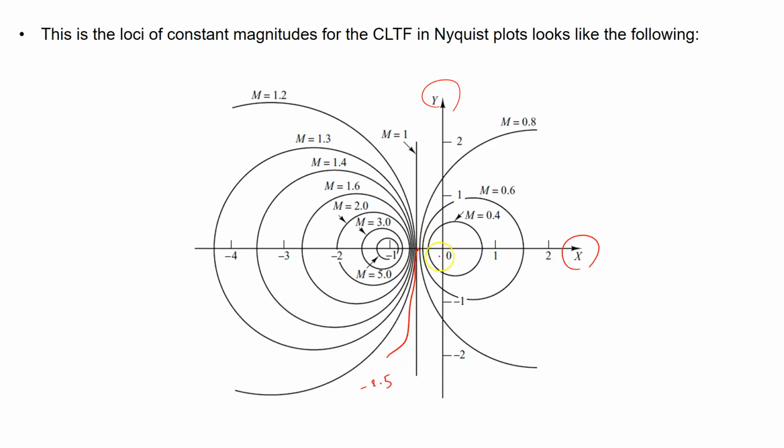So now if I have this on top of that Nyquist plot that you saw, that Nyquist plot was plotted for K equal 1. And I want this curve to intersect what M value? M of 1.4, which is this one. You see right now, this is M of 1.4, and this is the Nyquist of G. They are not going to intersect each other.